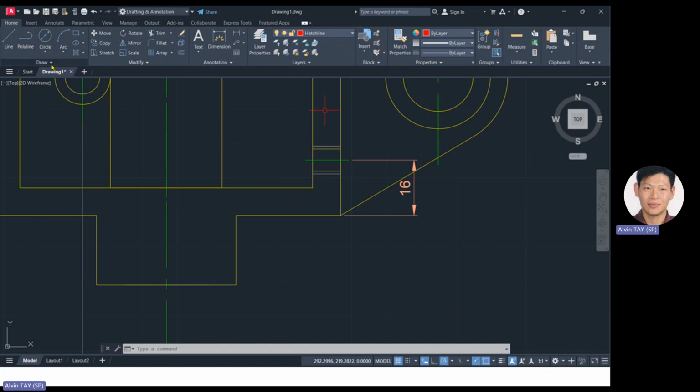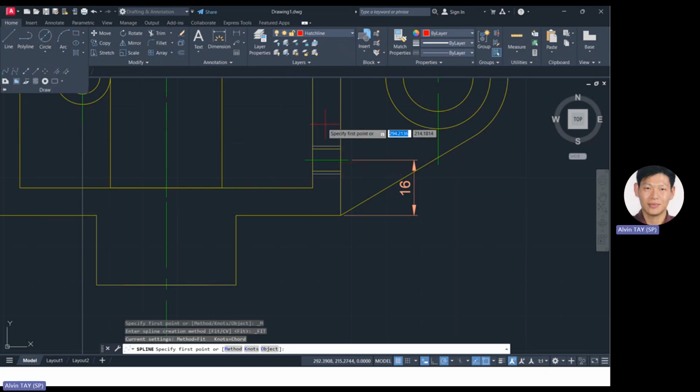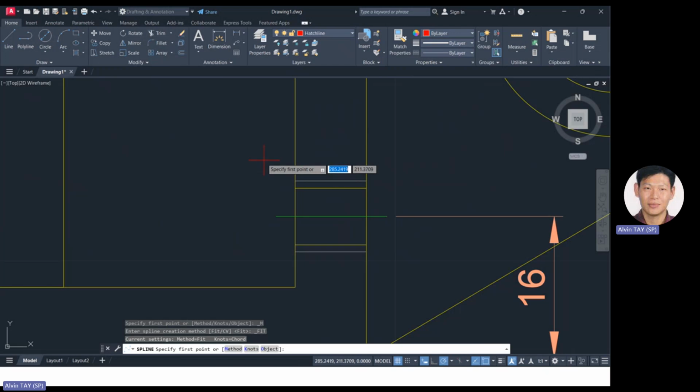Spline can be found under draw. There is this called spline fit. Okay, the second one you can adjust later. Yeah, I can adjust, but usually I don't. Okay, so I click on the outside first. Click outside, draw like a wave, and click on the outside. One time, press enter. Don't go and press escape. All right, do the same thing on the other side, underside.